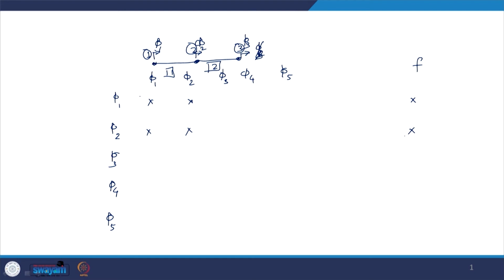So, this comes from element number 1, because element number 1 is defined by phi 1 and phi 2, and those elements will go here. This is K 1, the stiffness matrix of element number 1. So, 2 by 2, and these are the 2 elements of the first element load vector. Element number 2 is defined by variables phi 2 and phi 3.